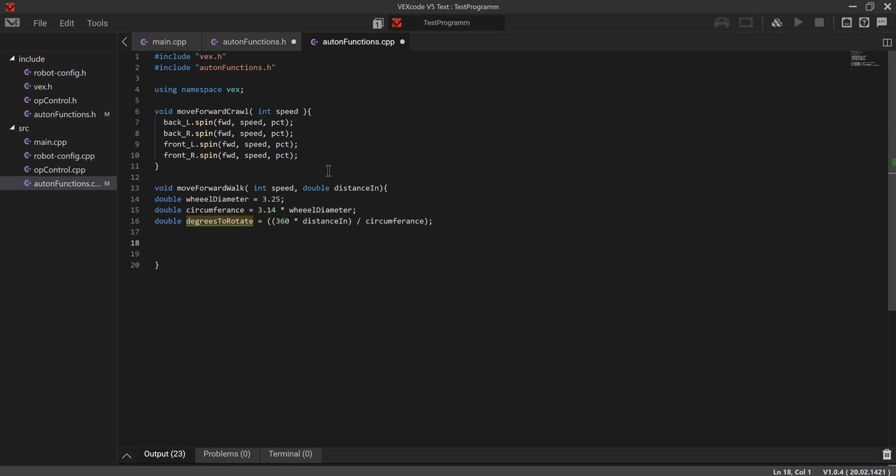Now we're going to be using something integrated in the motors themselves called IMEs, integrated motor encoders. Basically, they're like normal encoders, but now they're integrated in the motors. We'll get to what trackers are later on, but for now, let's stick with integrated motor encoders. With my personal use of them, they're a perfectly good way of estimating distance, and they're accurate as well.